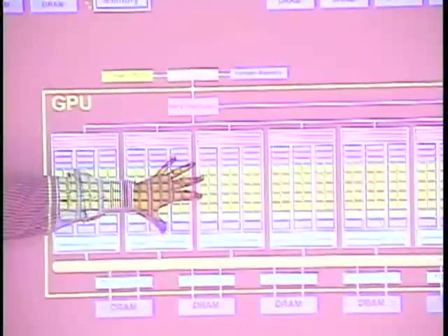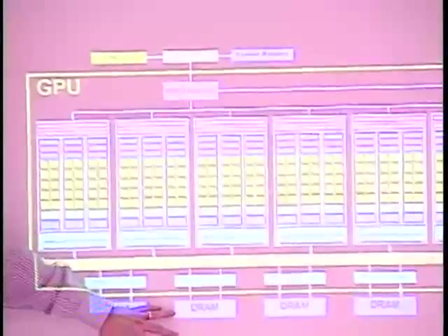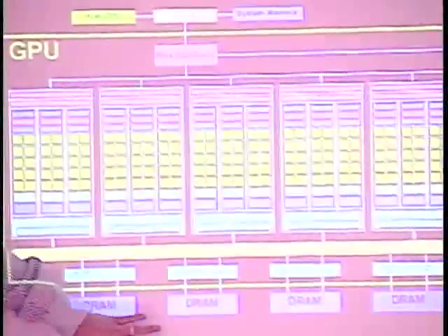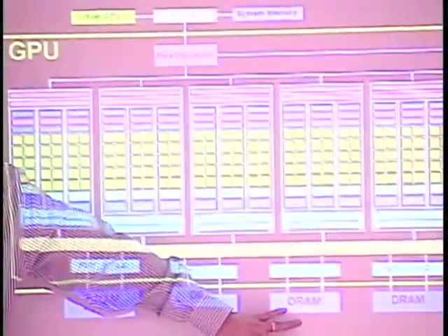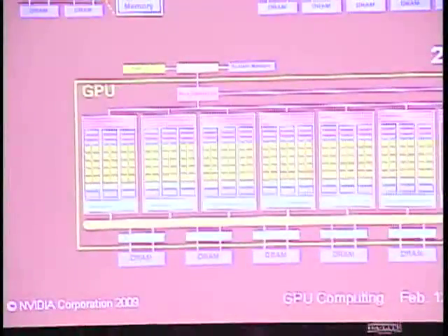And then physically the number of pins here. This GPU chip has over 2,000 pins on the package. Okay, and there are 512 data pins alone just getting to the DRAMs, plus all the address and control pins. There's a lot of pins going out to DRAM.